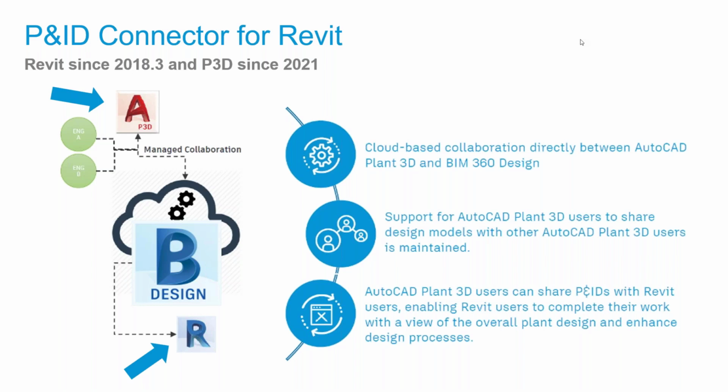So you can map all the catalogs and specs from AutoCAD P&ID with the Revit services into Revit MEP, the MEP part of Revit. It needs a bit of preparation, and you have a lot of mapping to prepare, but then it works. This has been reactivated since 2021, and you can use it straight away now.